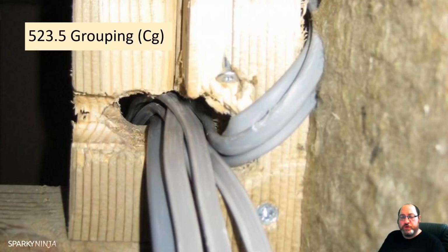But one of the things that they often will do, especially in consumer units, is that all of the neutrals will be nicely tied together, and all of the lines will be nicely tied together. So you end up with just this large brown bunch, and then going to fine little MCBs. I appreciate it's a good looking job, and I'll be honest, I did it a lot like that myself for a long time. The problem with that is if the designer hasn't considered that bunching effect, then there could be a problem with the overall current carrying capacity of the cable.